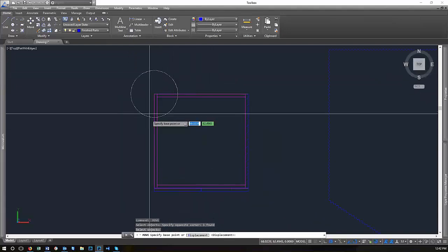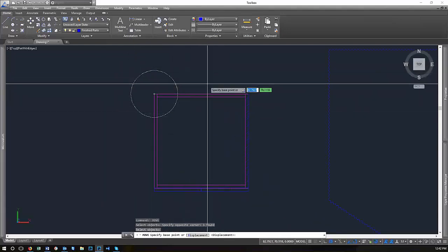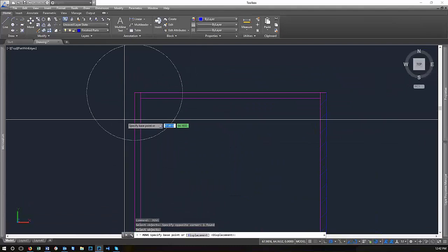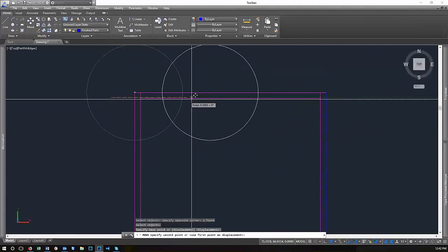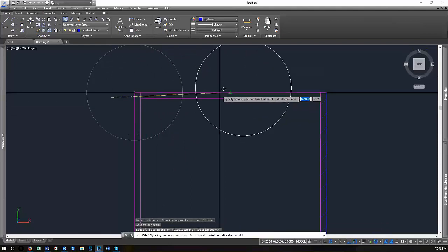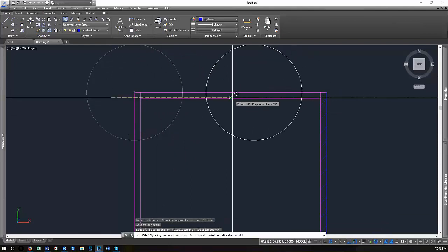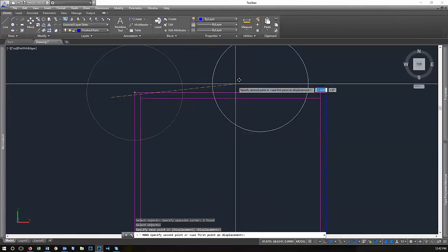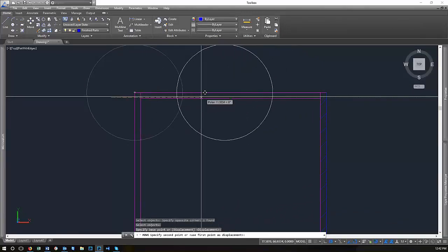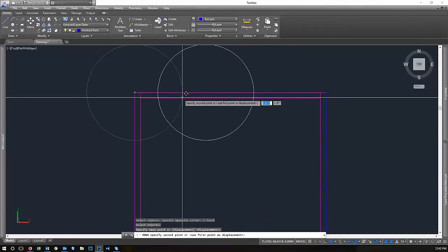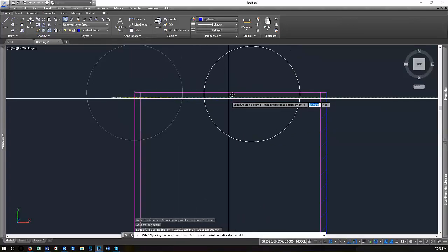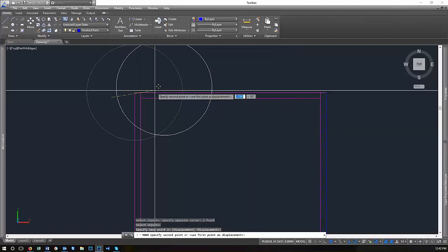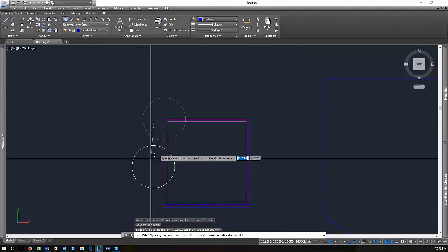Because if I say I want to move this over to the right, again, at 12 inches, I could click here. But then when I move over those 12 inches, I'm going to start getting snap points along my drawing. So that's going to interfere with my placement of this at the exact point where I want it, because I might accidentally hit this point or hit this grip point, or sorry, snap point, or some other snap point, and it's going to interfere with my location.